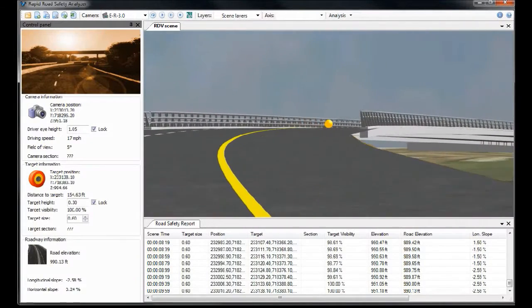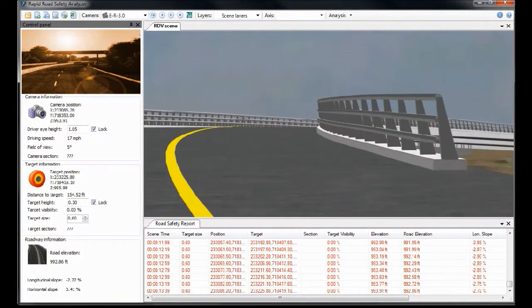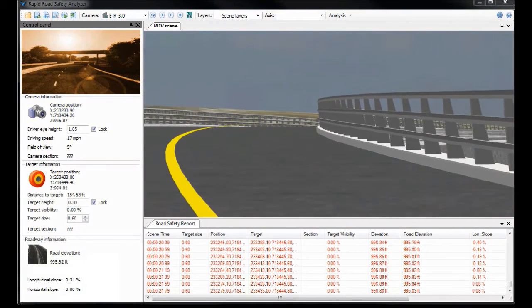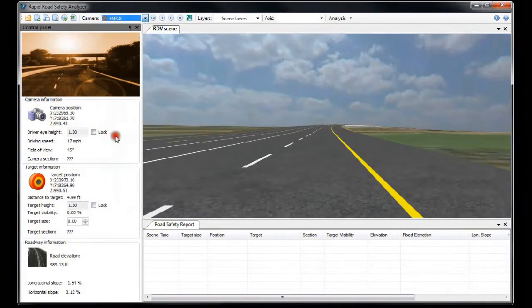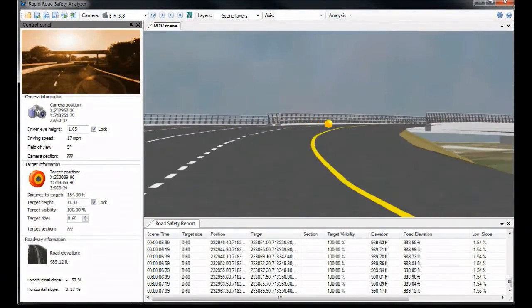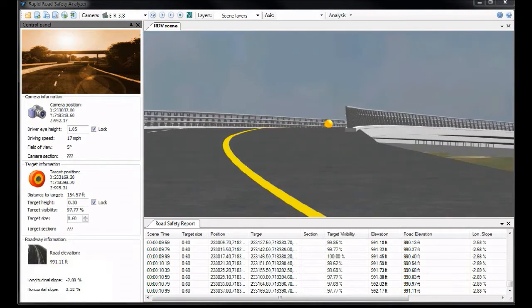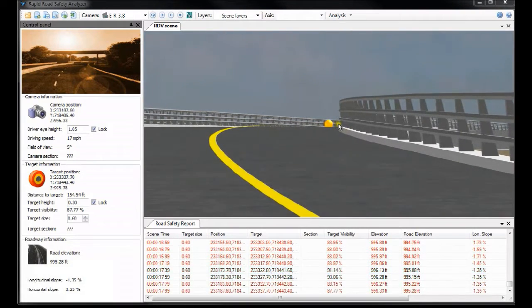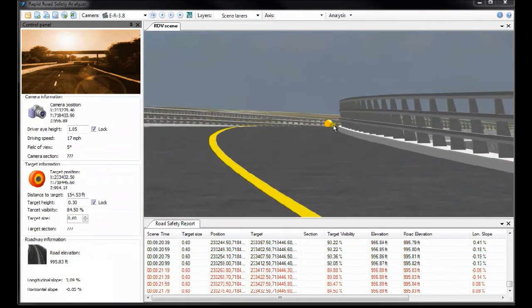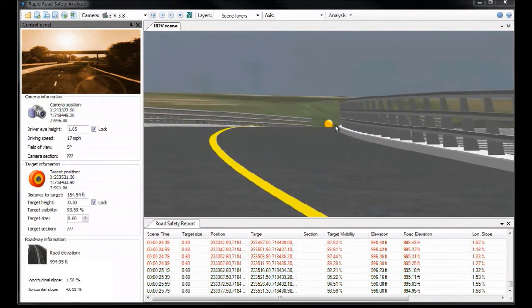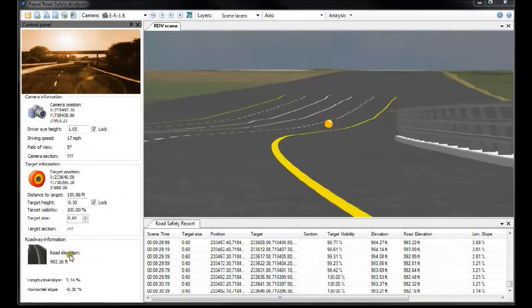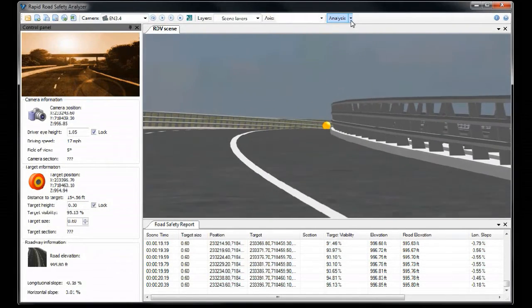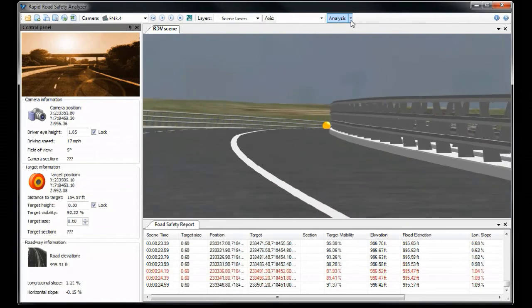Our initial run at the analysis looked at 2 different widths for the inside shoulder. Either 3 meters, which was the width originally proposed in preliminary design, or 3.8 meters, a width calculated by the geometric designer to address deficiencies for the required stopping site distances. After illustrating the obvious problems with the 3-meter option, a careful look at the 3.8-meter proposal indeed indicates that there may be room for optimization. Keep in mind that construction of shoulders wider than necessary, especially for bridges, can be quite costly.